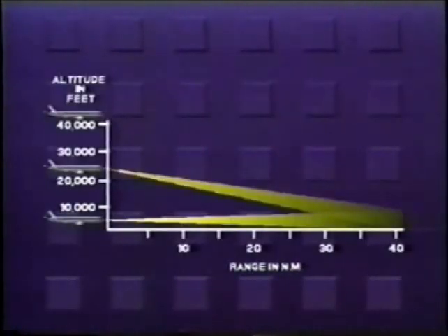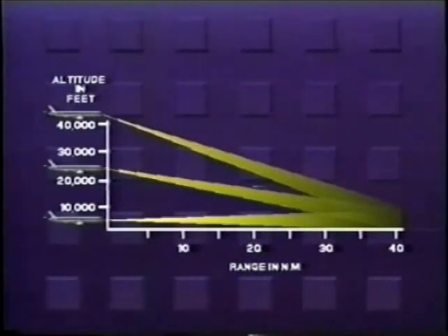Overscanning by setting the tilt too high is undoubtedly the most common mistake pilots make when operating a radar. If you change altitude, consider the geometry of the scenario. If you descend, you need more up tilt to display the correct radar picture. And if you ascend, you need more down tilt. You should adjust your antenna tilt each time you significantly change your flight altitude.